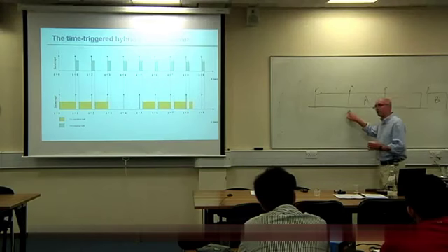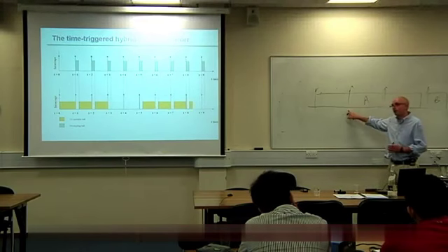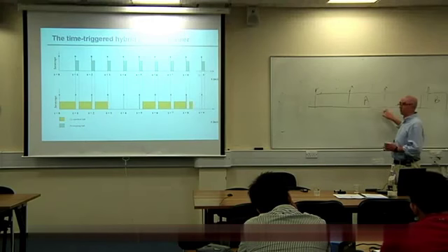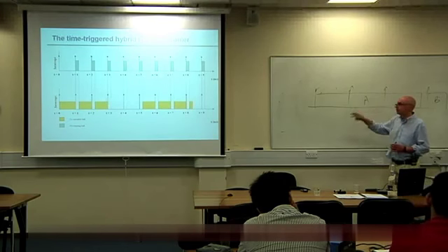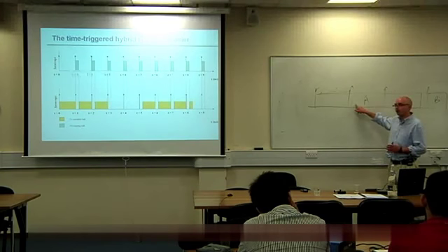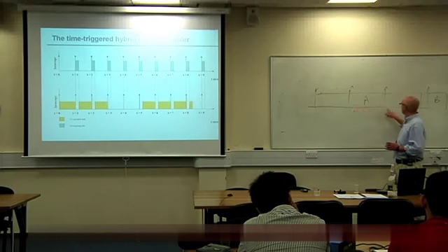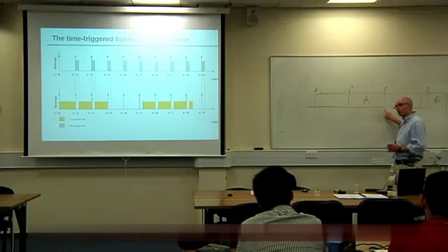So the interrupt occurs, we increment a tick count. The interrupt occurs, we increment a tick count. And we just go back in each case. We do that briefly, a very short period, and we go back to running A. So we're keeping track of the time, but that's not a problem necessarily.